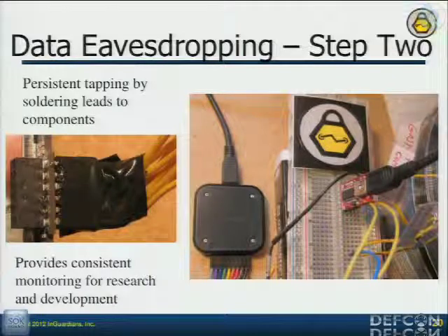And so we solder on that, and we pull those lines out onto our breadboard. Now we've got a more persistent connection, and we can put our logical analyzer on there. And if we understand how it's communicating, we can get devices and connect to those lines as well.